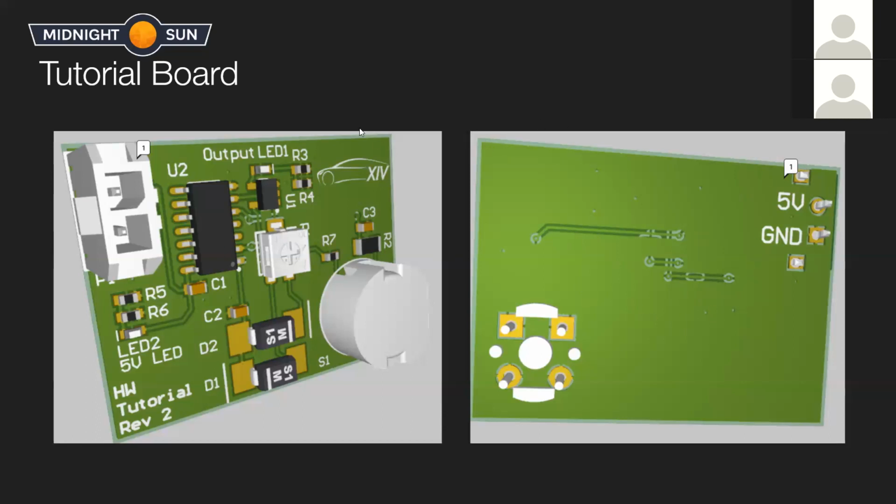Another thing to notice is we do use a keep out border. This is probably per the specifications of JLCPCB. I didn't actually check. So yeah, you'll notice that on most boards there's generally maybe just a couple traces, if any at all, on the bottom layer, for the purpose of having the whole bottom as ground.